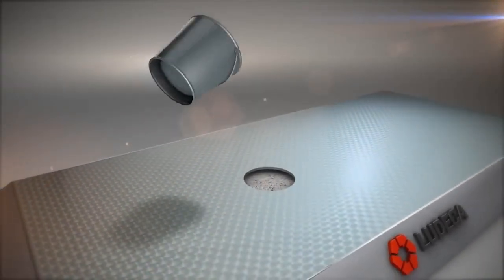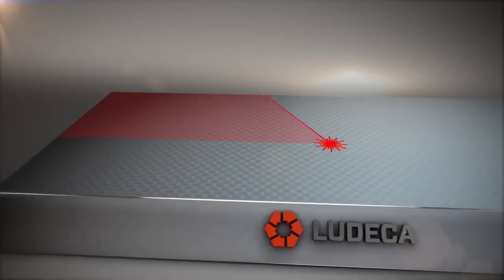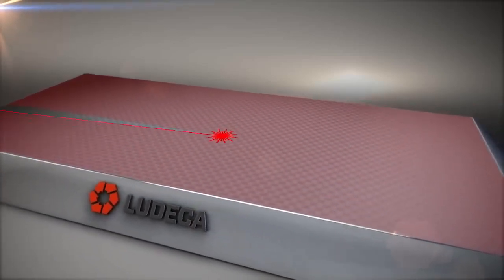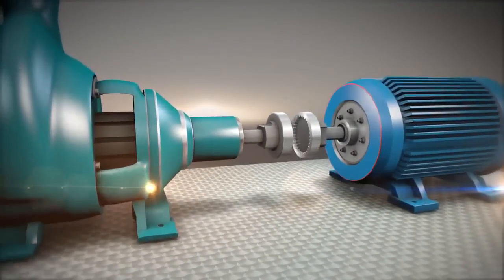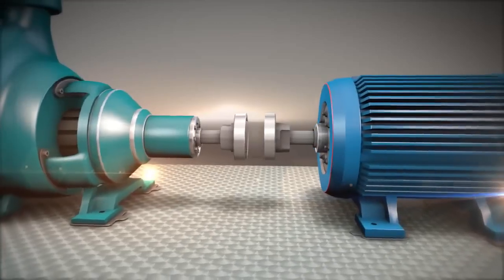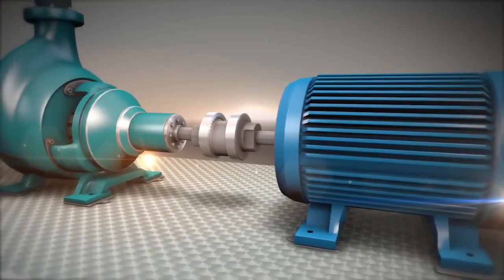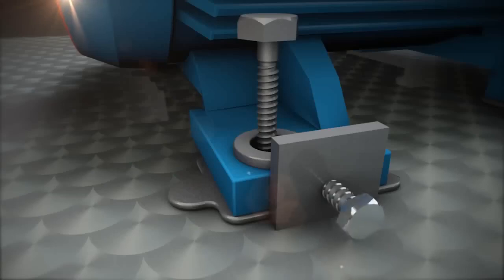Once we ensure that it is well prepared, flat and level, we can mount the base plate upon it and properly bolt or grout it to the foundation and ensure that it too is flat and level. With the base plate in place, the rotating equipment should be centered horizontally upon it and an equal amount of shims placed under each foot, while keeping the required axial gap. Installing jack bolts is also recommended to facilitate horizontal movement of the machines.